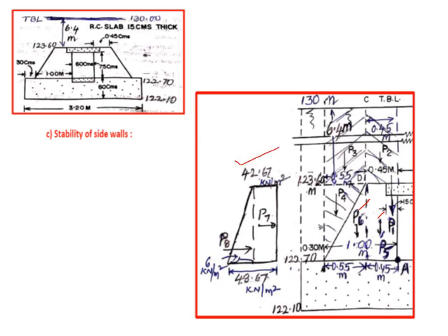Similarly, 6.4 plus 0.9 at the bottom, which will come to 7.3, that is 1/3 into 20 into 7.3 gives 48.67. You can divide into suitable portions, that is rectangular portion is P7 and triangular portion is P8. So what is the remaining ordinate for this? 48.67 minus 42.67 comes to 6 kilonewton per meter square. So in order to calculate P7, it is the area of this diagram, which is 42.67 into 0.9 into 1 is P7. Half into 6 into 0.9 into 1 gives P8.